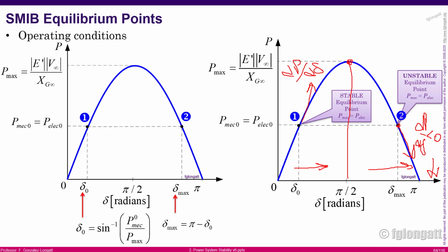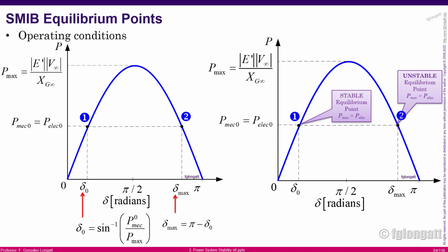And we don't want that because it's not helping to stabilize the system. In that case, you are reducing the active power, when the active power is more needed. And that is the reason that that equilibrium point is unstable, okay?